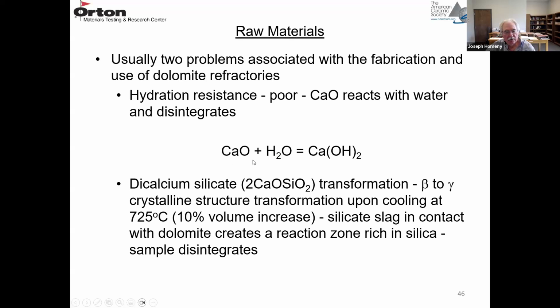And I've taken a fired dolomite brick, and you can put it on a table in my lab in Ohio in the summer where it's humid, and wait a month and come back and it's a pile of dust. So just with the moisture in the atmosphere, within a short time, it will completely hydrate and disintegrate. So its hydration resistance is a big issue on how you use these materials.